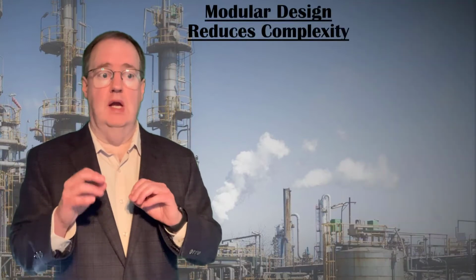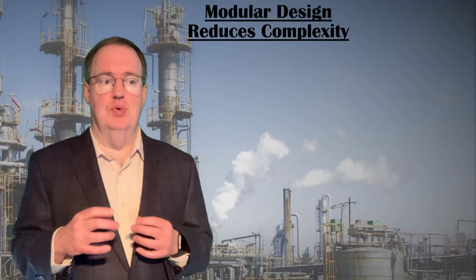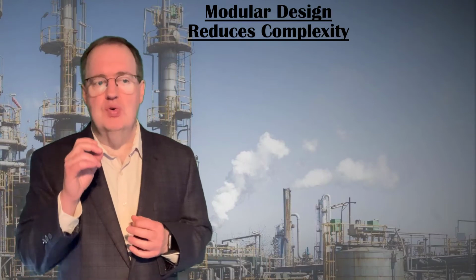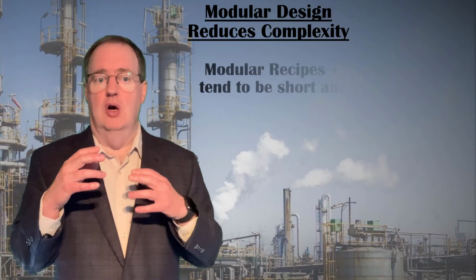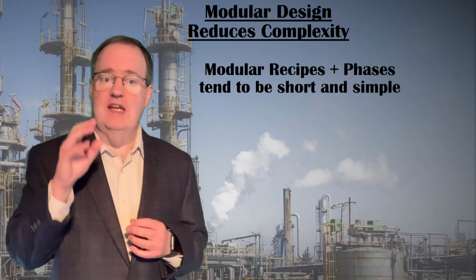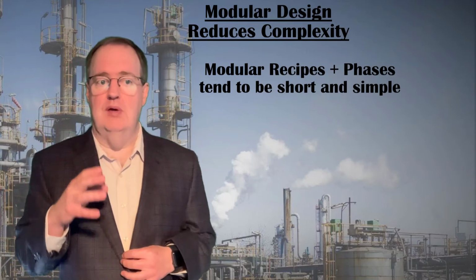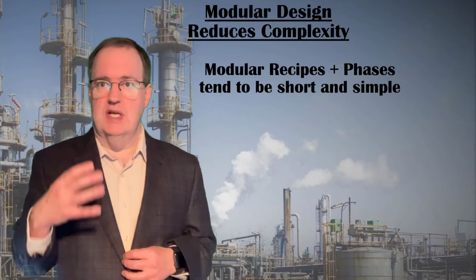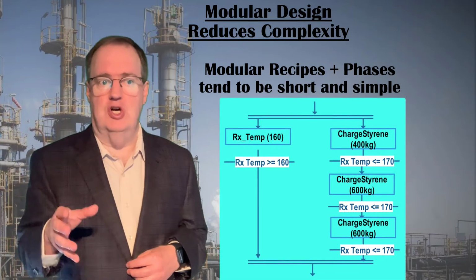The reason breaking up the batch into modules is worthwhile is that each of the modules is relatively simple. Most sequential function charts for a recipe or a phase are 1 to 2 pages, and more often 1 than 2. And they can be reused. A batch recipe for making polystyrene beads may need to charge styrene 6 different times, with a different mass target for each charge.